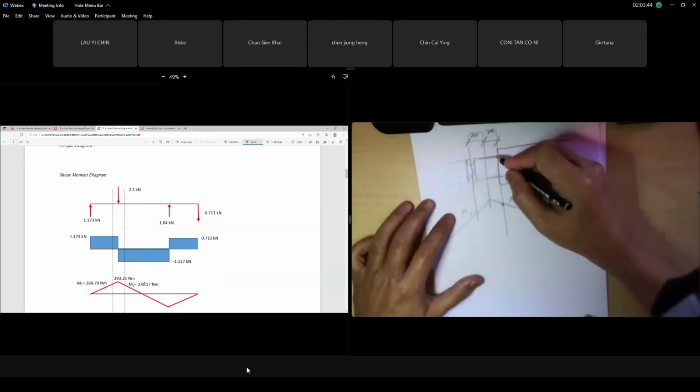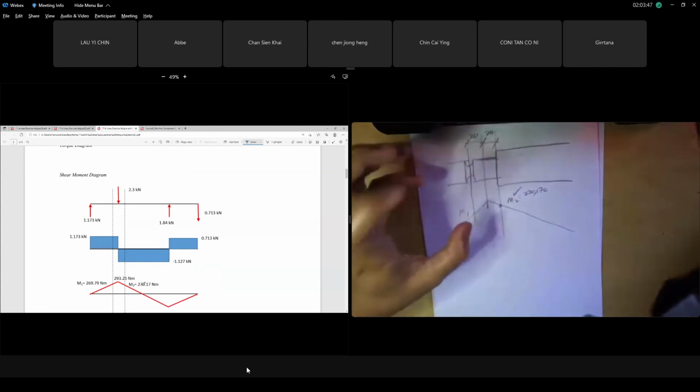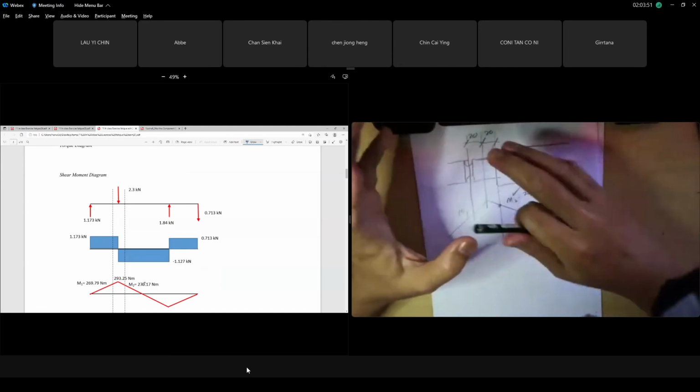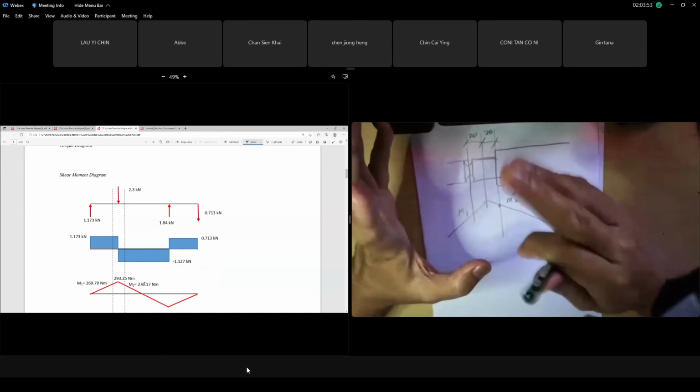Okay, you multiply, but be careful guys. Mind your case, your KT. Remember, your bending stress times KF bending. KF bending is 1 plus Q bending times KT bending minus 1.